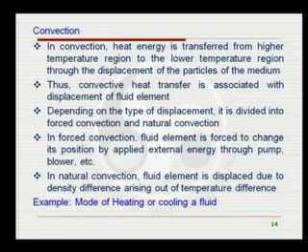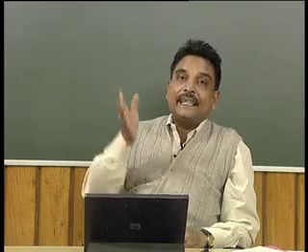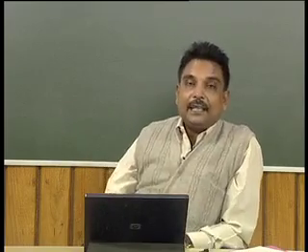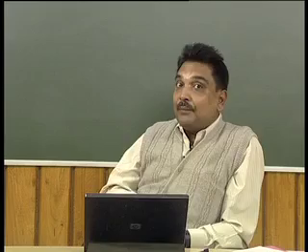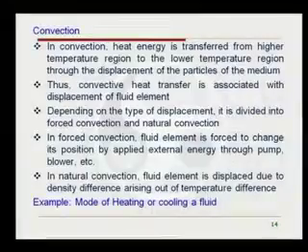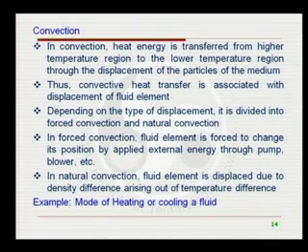Forced convection heat transfer means you are applying some kind of velocity to the fluid element to move it from one place to another by applying some external energy, and this external energy you can apply with the help of a pump or a blower. This kind of natural or forced convection phenomenon happens for liquid and gaseous or vapor substances.